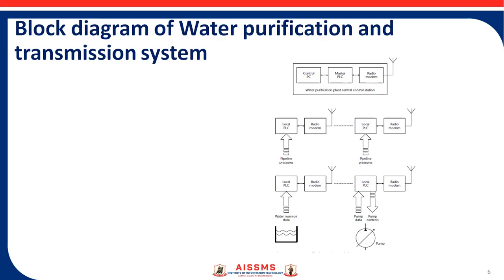Within the plant, process controllers or PLCs supervise unit processes such as chemical treatment and filters. A local area network, that is a LAN, such as Ethernet, links the controllers to the workstations as well as to one another. RTUs are used at remote sites and usually exist in pump stations, storage tanks, valve vaults, and treatment facilities. Today's RTUs are a rugged version of process controllers and operate in outdoor environments.